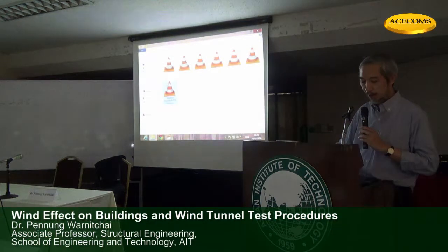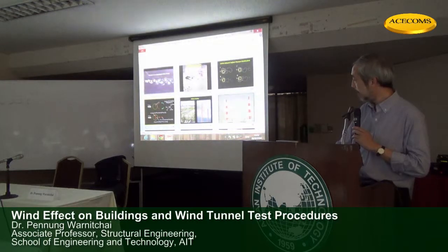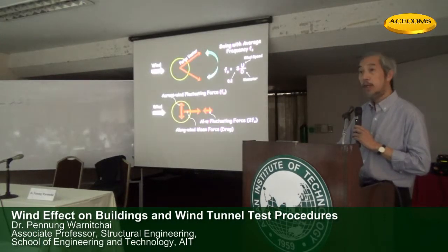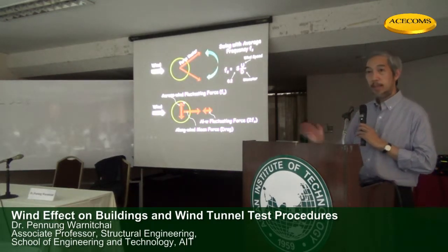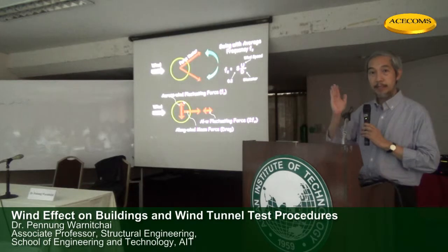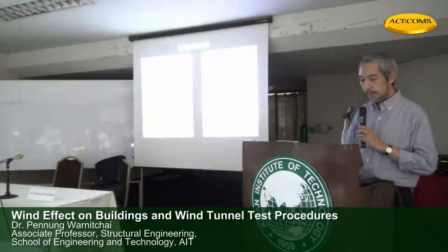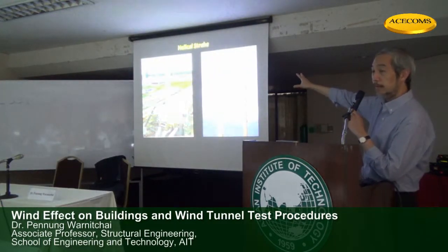And you don't want to be on the top of that tower. Okay, but it's created by this type of mechanism we call the vortex resonance. If this force happens to have a frequency match with the structure, it will produce this large crosswind response.